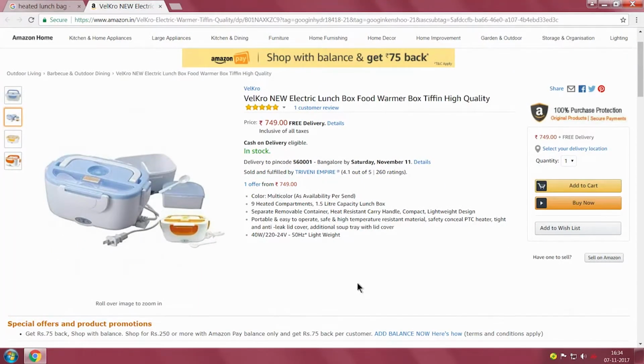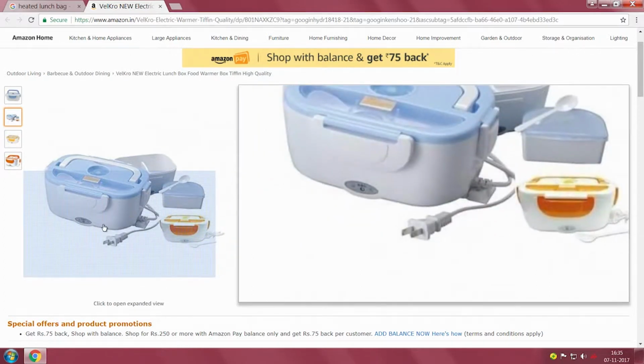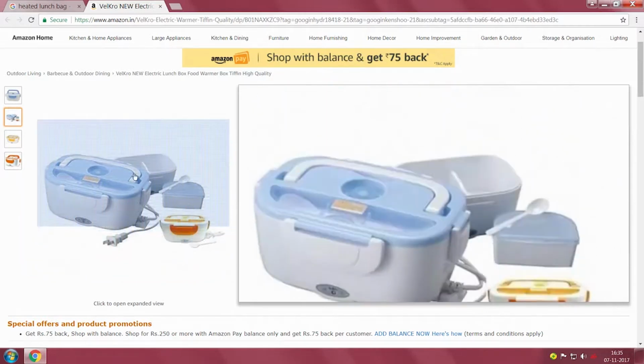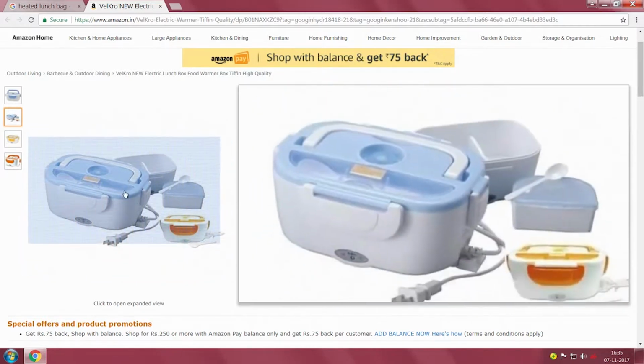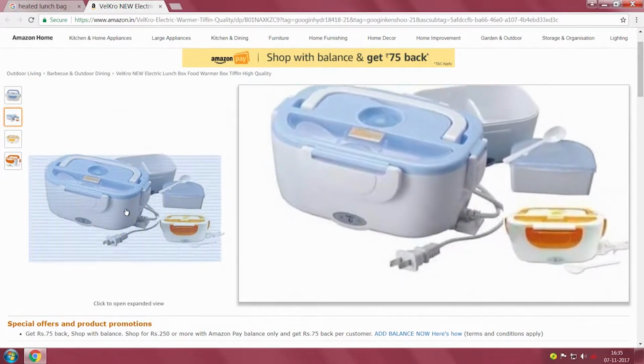Typically, I will see if he has written anything. Yeah, he says it is a 40 watt heater. So actually, it is a 40 watt with a little bit of control, probably a diode control. After it reaches a certain temperature, a thermostat switches it off and switches it on, or gets it into the low power mode. So typically, something like this is enough, but the beauty of it is about the insulation and about the rate of heating and total mass that is included in it.